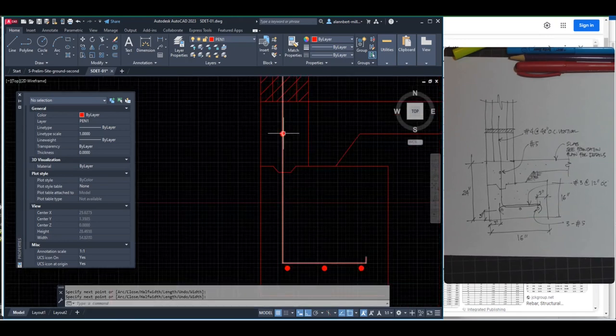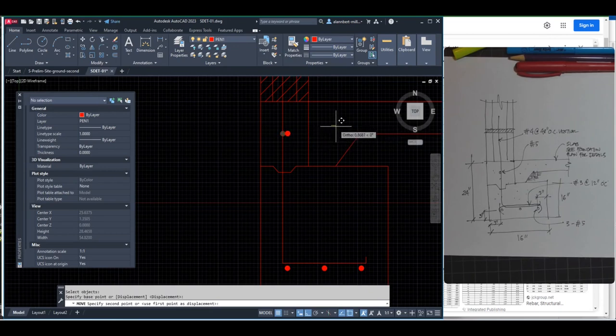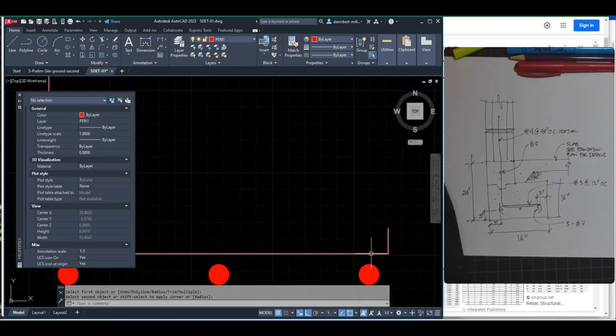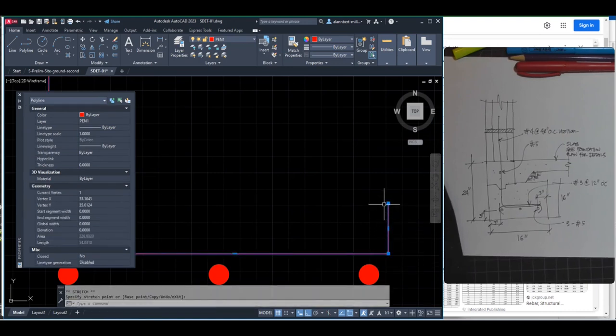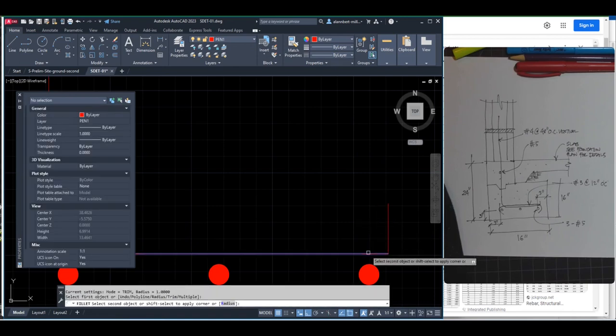And what we're going to do is we're going to move this down a little bit, and we're going to do a fillet radius here. So I'm going to type F for fillet, and then I'm going to click in radius, and I'm going to put in a radius of, let's say, 2. Enter. So I'm going to click this and that. That's too big, so I'm going to undo fillet radius and type in only 1, and click this and that. There you go. And this one, fillet again, click this and that. Whoop. Maybe I need to move this higher, and then so my fillet will work with the radius of 1.